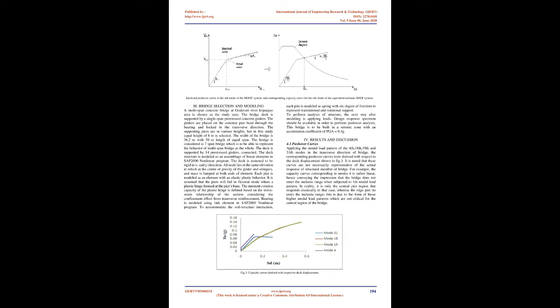A. An extension of the standard pushover analysis. B. Modal pushover curves are then plotted and can be converted to SDF capacity diagrams using modal conversion parameters based on the same shapes. C. Compute the natural periods, Tn, and modes, φn, for linearly elastic vibration of the structure. D. Carry out separate pushover analyses for force distribution, sn* = mφn,